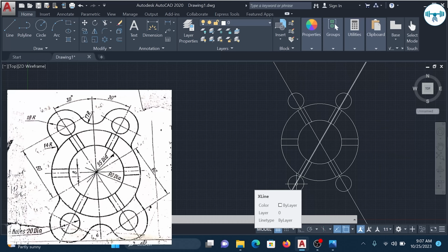Don't worry, I'm going to show you how that's done. But the important thing is that we are going to draw the complete circle first before we start the operation. One principle in AutoCAD and generally in engineering drawing is that, in tangency, whenever you're dealing with a tangency problem, you draw the circle first before you start thinking of how to connect them. So for these four new circles, we are going to draw the complete circles first, then we start connecting them with the different radii given.